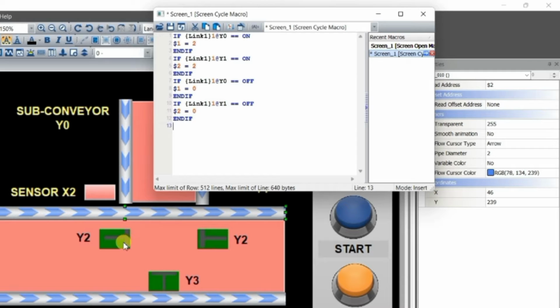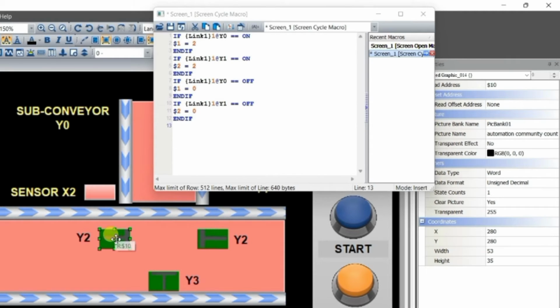We have to write animation code to move this image. These are the pistons. Because we are not using the actual outputs, we are using the animations of HMI to visualize our project. So for animation, we need two positions, initial and final. So first of all, this is the initial position. From here, let us select this is our final position. So you have to move your desired object to that final position. Now we will write code for this.